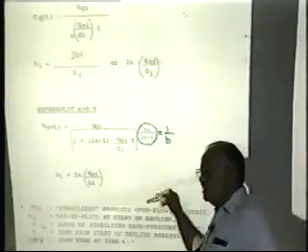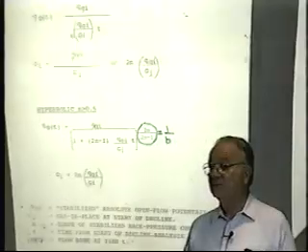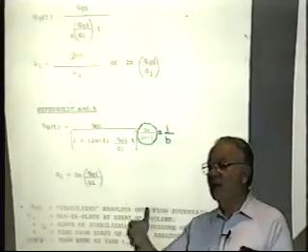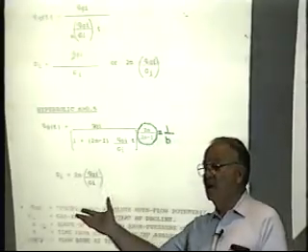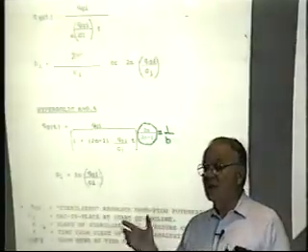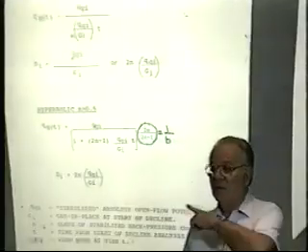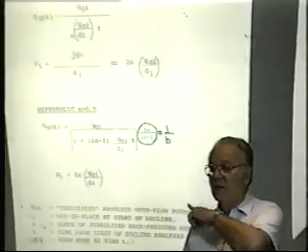Your Q sub i is a point on a stabilized back pressure curve. That's all it is. So if you have a KH and a skin from a build-up test, you just take the basic flow equation for pseudo-steady state. You calculate the back pressure. That's the Q sub i.